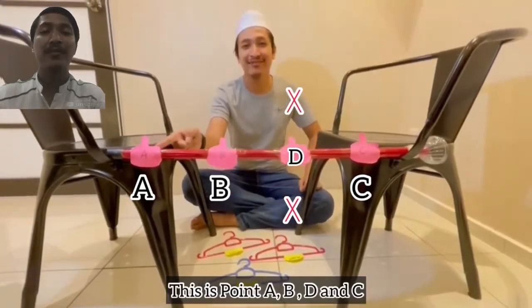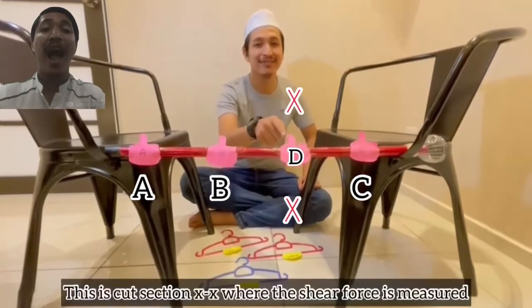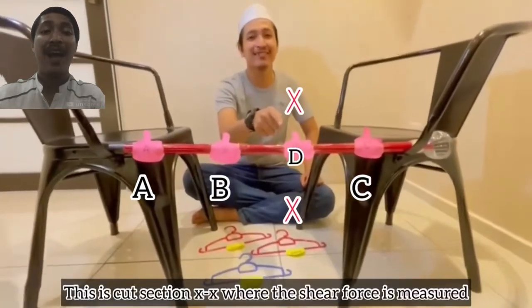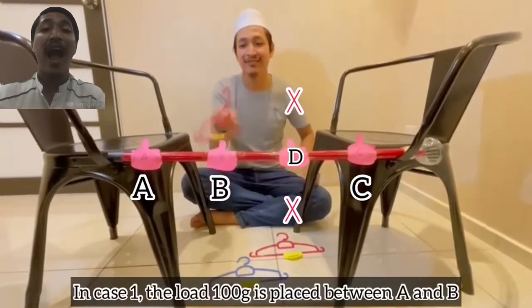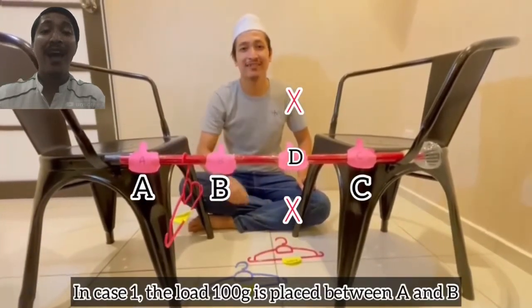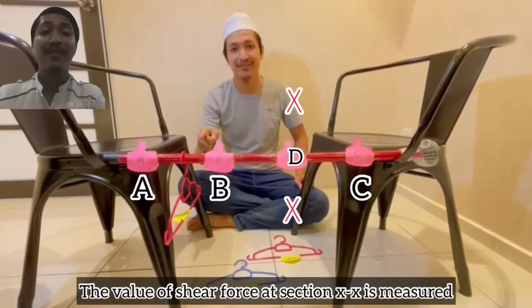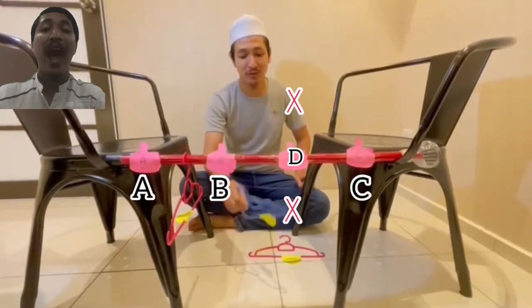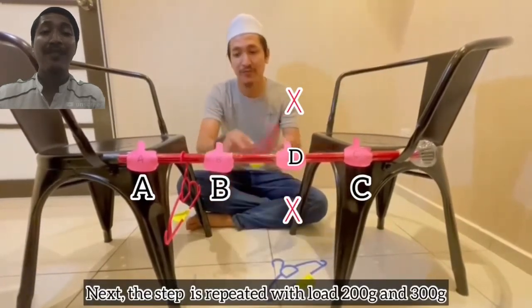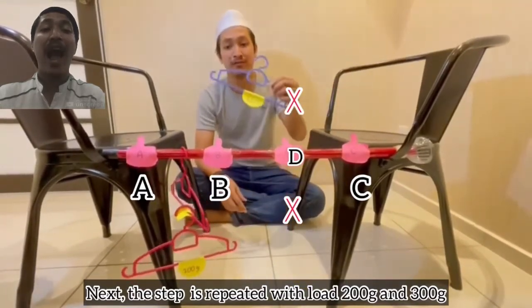This is point A, B, D, and C. This is the cut section XX where the shear force is measured. In case 1, the load of 100 gram is placed between A and B. The value of shear force at section XX is measured. Next, the step is repeated with loads of 200 gram and 300 gram.